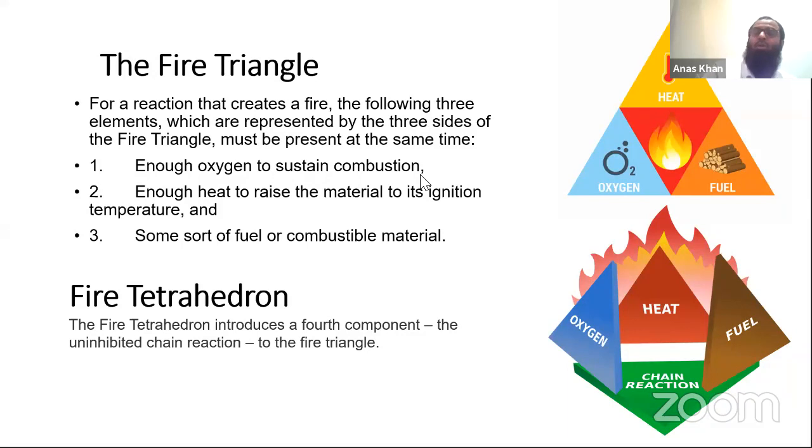See, even a small amount of ignition is enough, because it depends on the property, again, as I told you. If it is petrol, high octane, no problem. If it is a lighter product, more problem. If it is a lubricant oil, no problem. If it is your cooking oil, no problem, right? But the lighter it is, the more problematic. Spirit, ethanol, methanol, all these are problems.